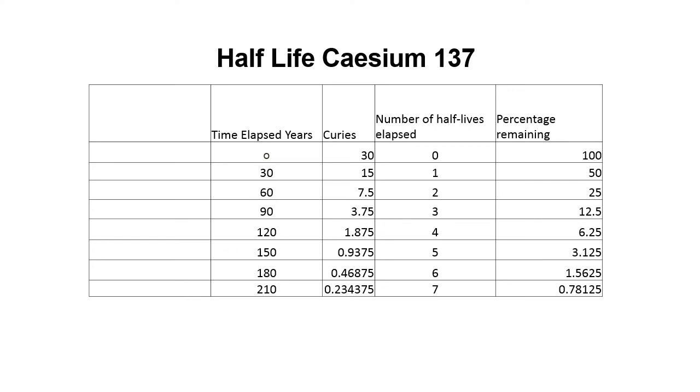And you look at this from a standpoint of a half-life of something you're going to use to do radiography. Well, with a 30-year half-life, you can do a lot of radiography before you even get down to 50%. So even at 30 years, you're down to 50%. 60 years, you're down to 25%. It's like I said, it's a big difference from Iridium and even from Cobalt with its 5.27 years of half-life.